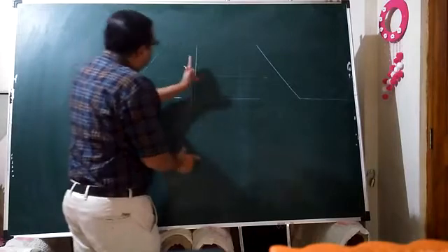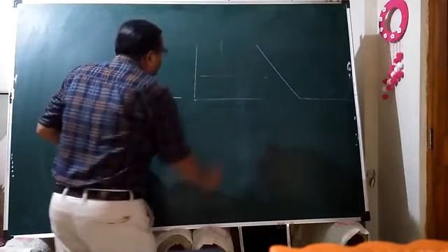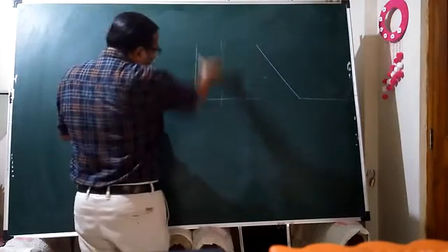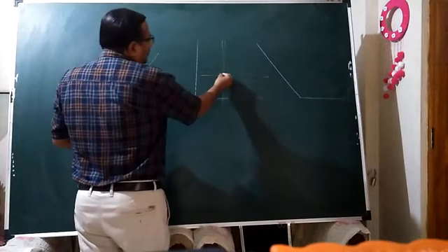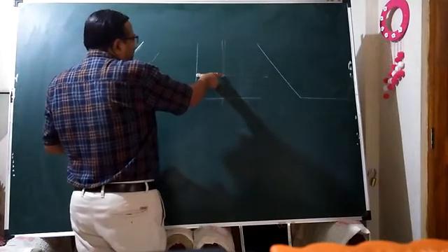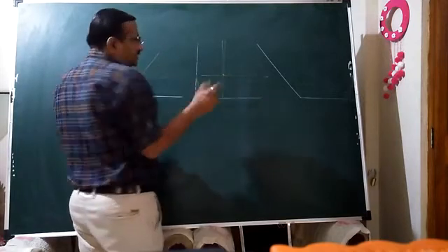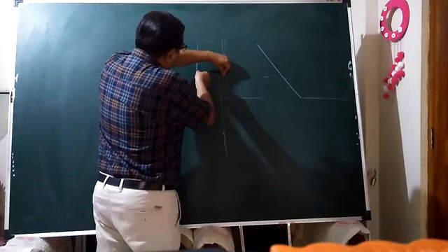Similarly, get a line vertically 30 mm departed from this line. Same distance of 30 mm vertically. Hold the scale here, and by compass get that line. The intersecting point will be here. Now from this point, by compass, you connect these two lines in this way, with the same 30 mm distance.